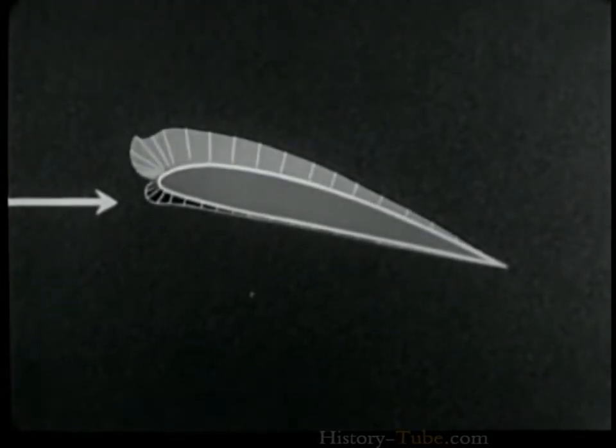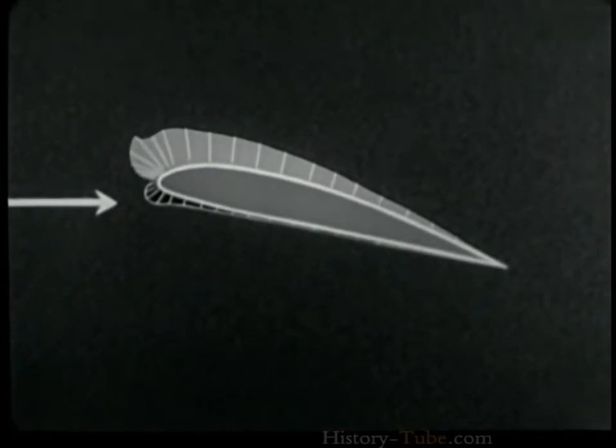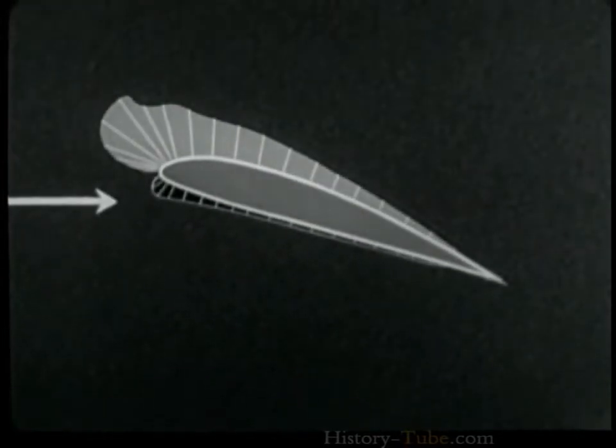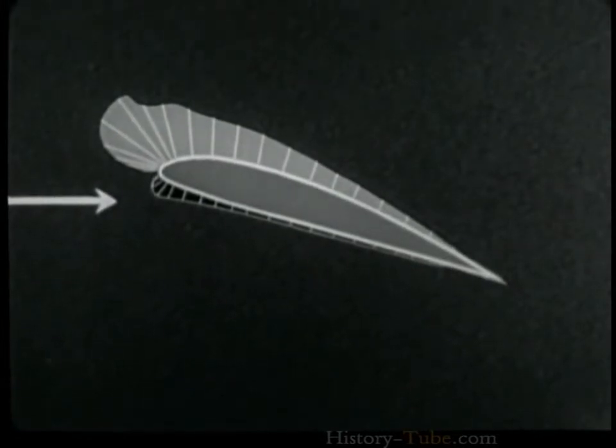The wing is now approaching its stalling angle. Positive pressures have changed very little in either distribution or value. The negative values, however, have increased somewhat, especially at the leading edge. By further increasing the angle of attack, positive pressures remain practically unchanged in both value and distribution, but the value of negative pressure continues to increase.